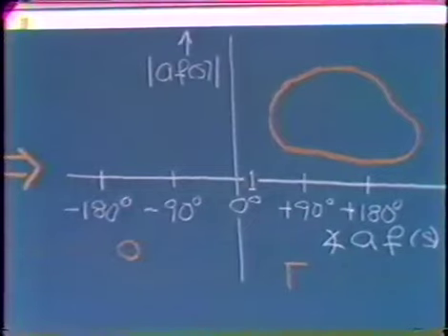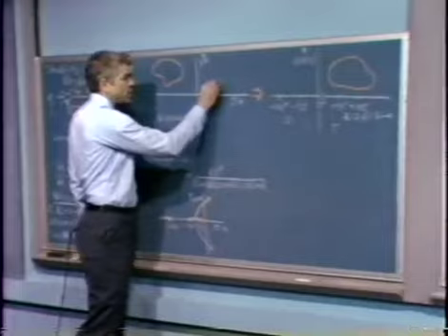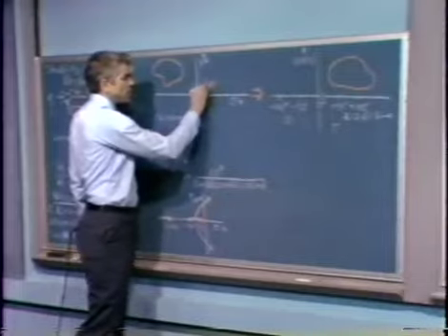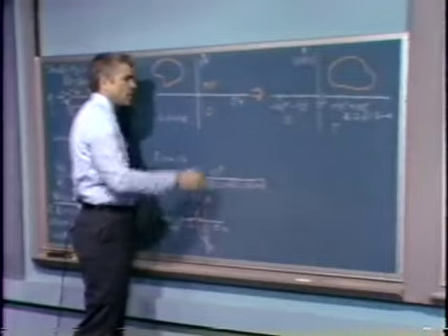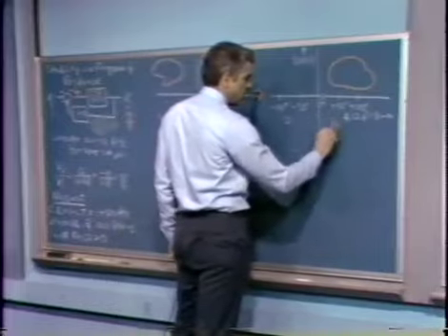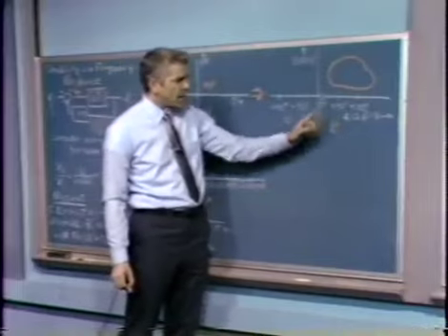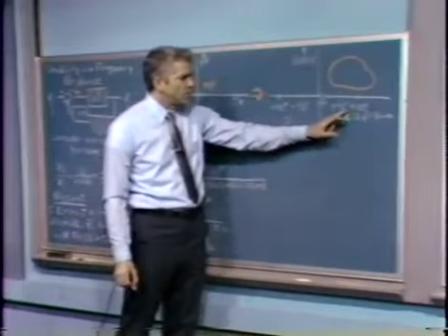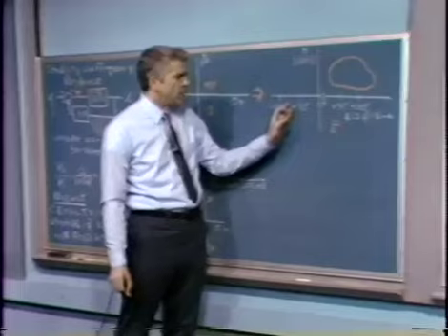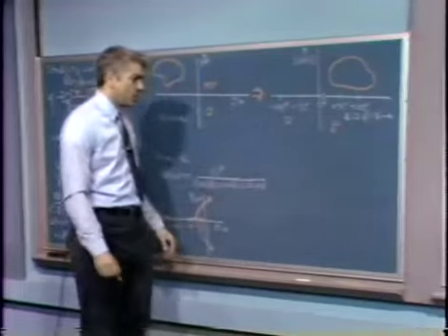As it happens, because of the choice of coordinates, when we make a right-hand turn in the S plane, in other words, if we evaluated AF along this path in that direction such that we took a right-hand turn, we'd find that we actually take a left-hand turn in the AF plane, and that simply has to do with the choice of axes for the angle. Had we chosen to plot positive angles to the left rather than as is conventionally done, the right-hand turns would have been maintained.